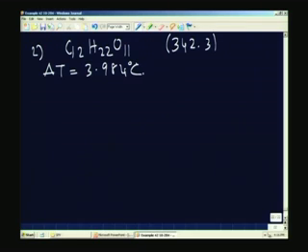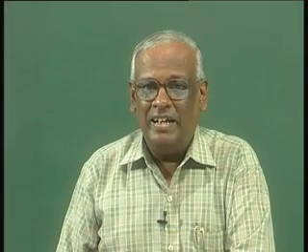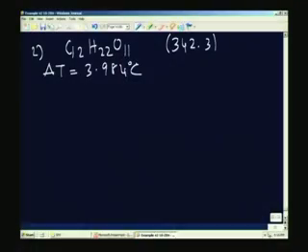The same calorimeter is used, therefore the capital C is the one found in the previous experiment. You will also notice that in the case of sugar, there is no change in the moles. The number of moles of gas on the right hand side, CO2, is the same as the oxygen. Therefore, whatever heating value you obtain is automatically both the enthalpy and the energy; there is no difference in those two quantities. Therefore, I do not have to worry about that. So, we will say that delta n equals 0.